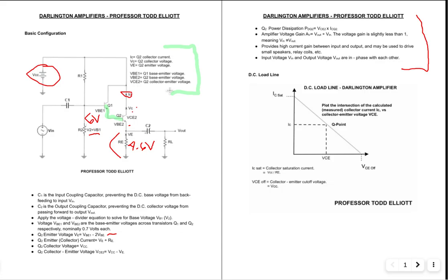Okay. The amplifier voltage gain, in general terms, look at my other videos, I think it's called Solving the Darlington Amplifier, if you want the full show. It is simply the ratio between the output and the input. Unlike the common emitter amplifier, there is no phase shift at reasonable frequencies. We're not talking about high frequency effects, but the input and output sine waves are in phase.